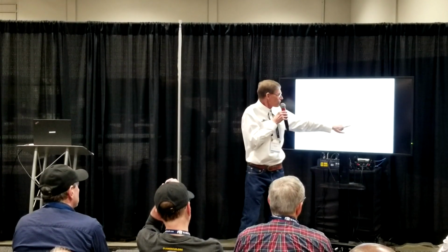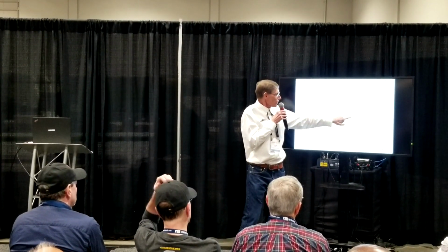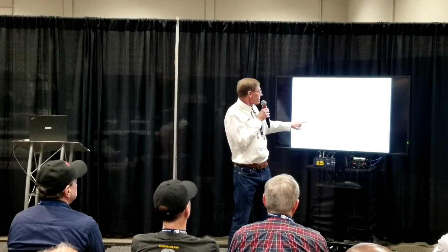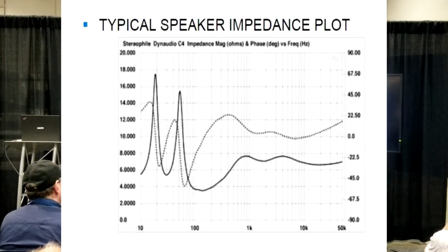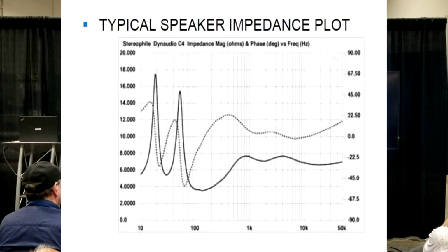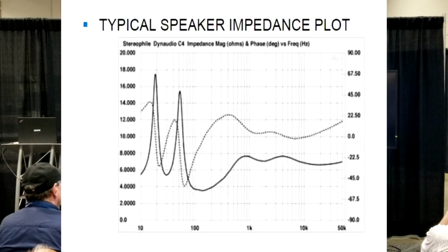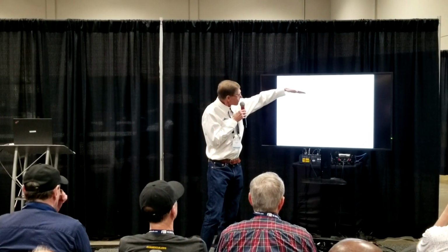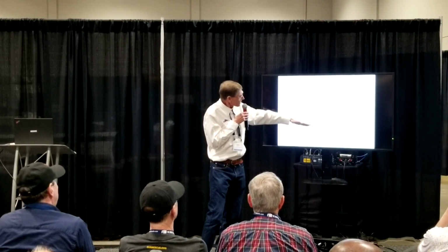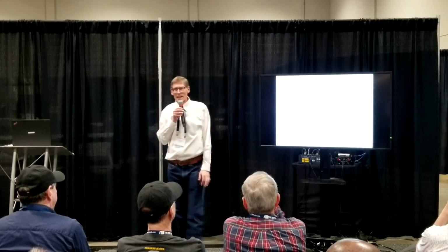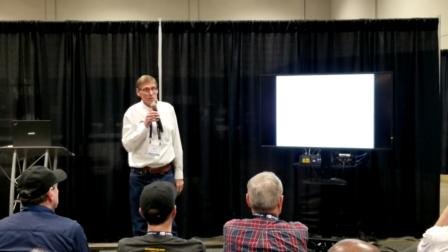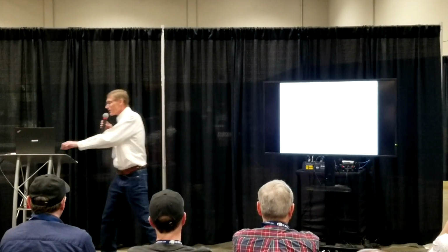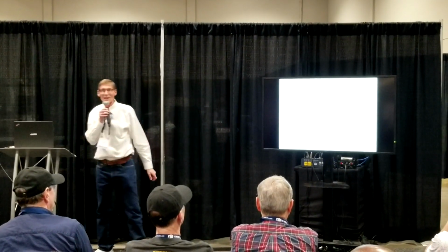And it's always lower than this value. As long as this value is above it, it's going to tell you this impedance is really, at that frequency, not really the impedance you think it is. So in other words, it's going to drive your amp nuts. But this is 18 ohms, roughly, peaks here and here, nominals kind of down. But that ain't even close to our cable. Our cables, you won't believe me, we're going to see in just a minute, our cable's quite a bit higher impedance than that.